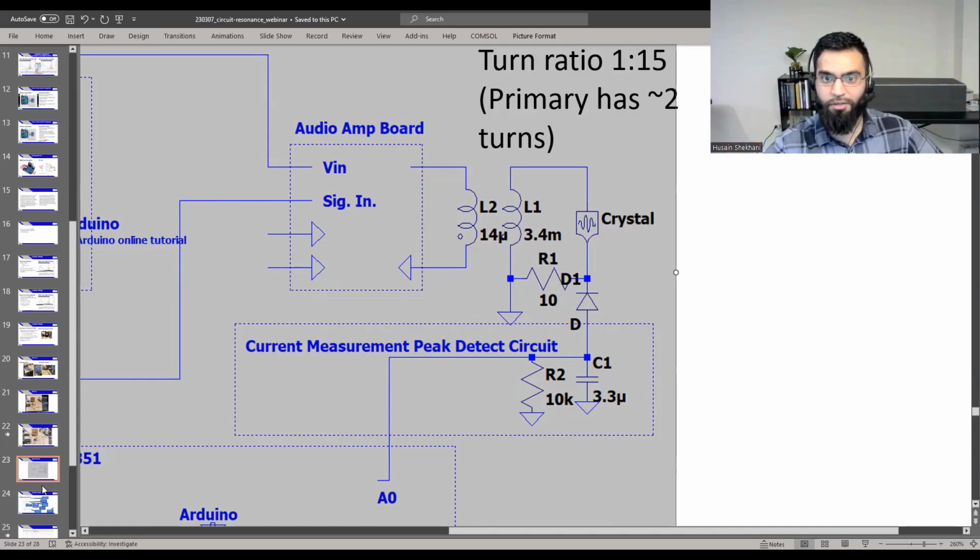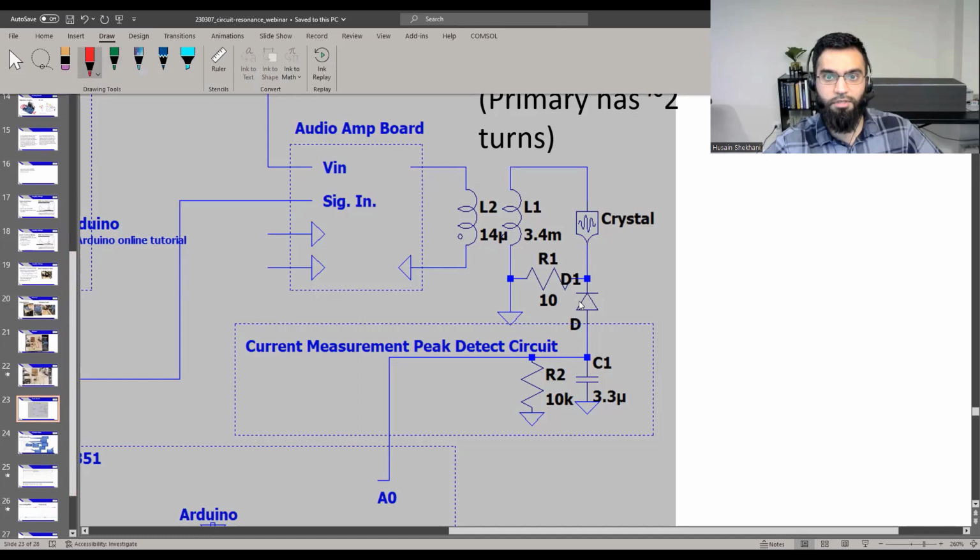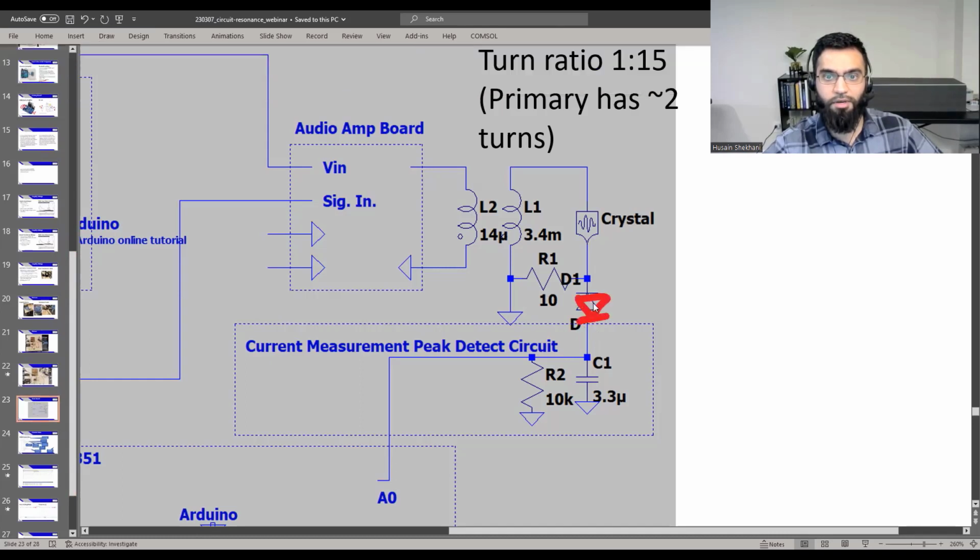And yeah, it worked. It didn't fry, and I did an oscilloscope measurement first to make sure the voltage was good, not out of range. And it's only going to be positive, right? Because the way the diode is switched, this should be reversed. I'm just going to do it right now instead of having to say it 100 more times. So it'll allow current to come up and charge that capacitor, but it won't allow it to drop.